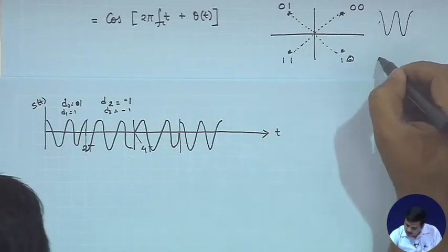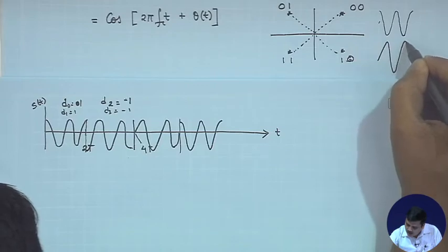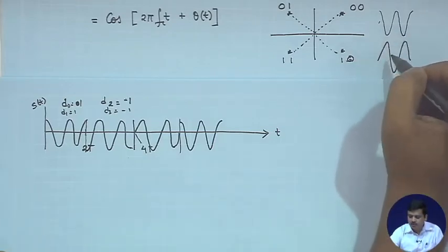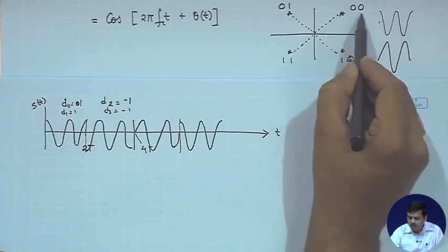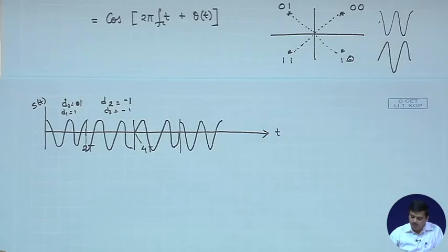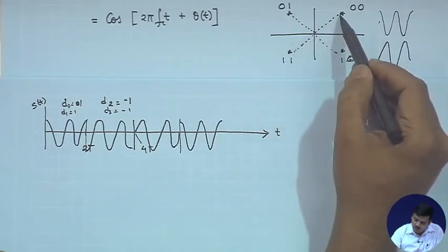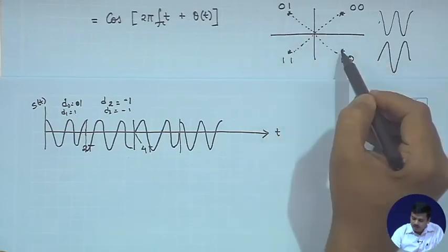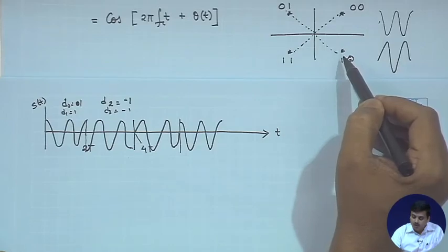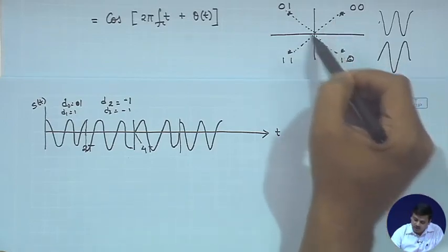So, you could get another waveform. Similarly there would be 2 other waveforms. So, for every 2 possible inputs you would choose any of the 4 waveforms that are available with you. So, what could happen at every 2t interval is that the phase of the carrier could change from any point to any point. What is worse is when the phase changes by 180 degree.